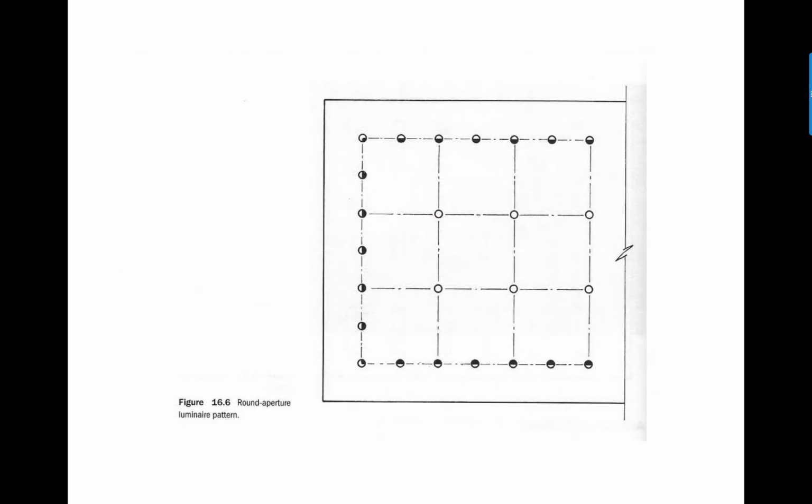But anyway, the book does talk about kind of typical lighting layouts. Again, I'm not quite sure why this particular diagram was in the sustainability chapter, but this is a very common thing. These wall wash fixtures, you'll notice the icon for the fixture is dark on one side, light on the other. That's the standard. This is a corner wall wash, and you can also get double wall washes, which are great for corridors. These are downlights, okay? And this is a typical pattern that you'll see. If you wanted a room that has a sense of spatial quality, you can wall wash pretty continuously all the way around, and then downlights in the middle.